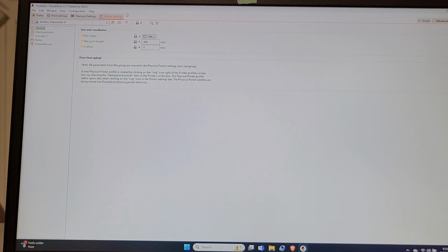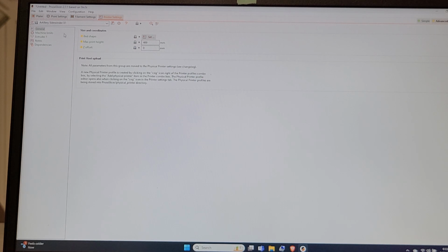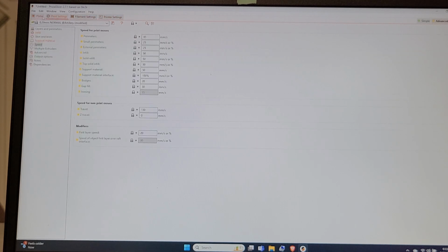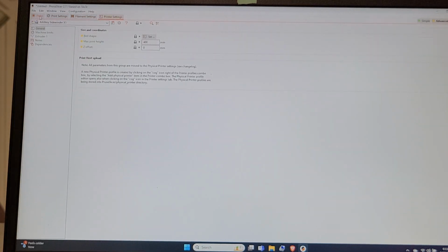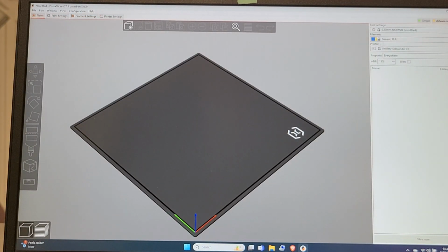And if it looks like it's too low or too high when it's printing, because you can do a lot of visual checks too, then I'll just adjust the knobs on the bed, because mine only has manual. But those are the basic things that you'll change for your prints if you're trying different stuff out.